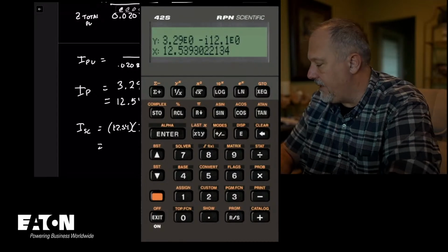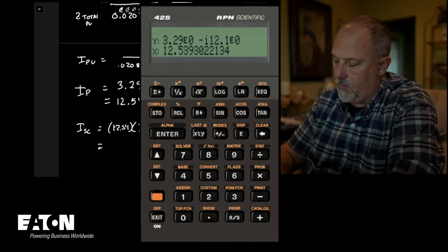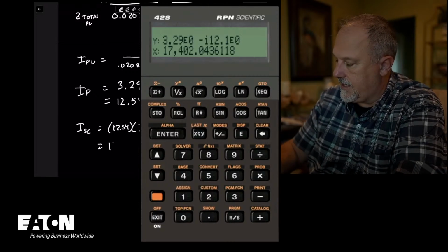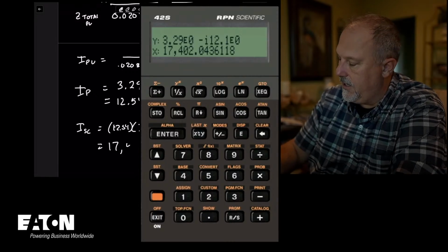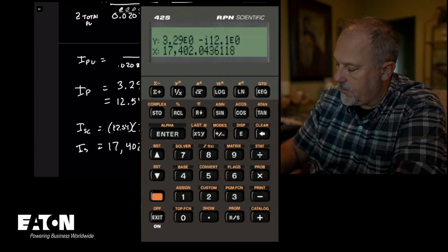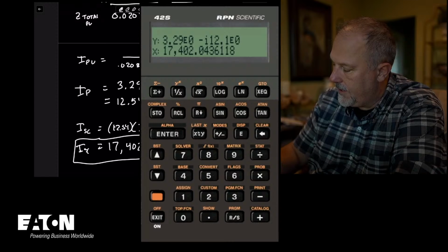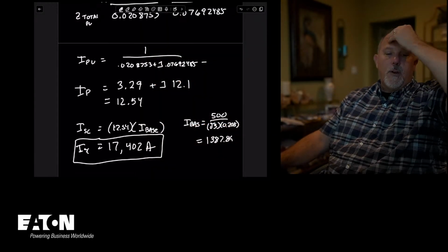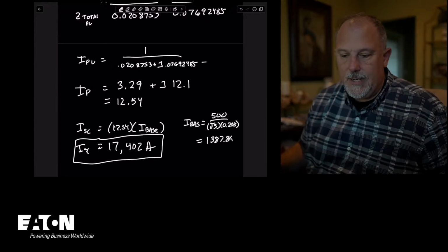I don't know, 8. I'm going to call it 8. 1387.8 times that is 17,402 amps. I short circuit. All right. So 17,402 amps.